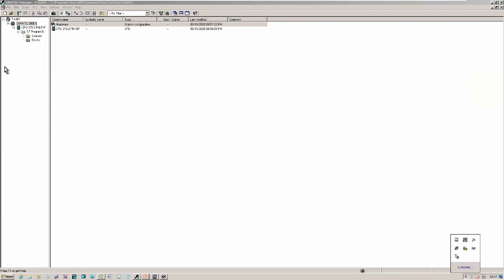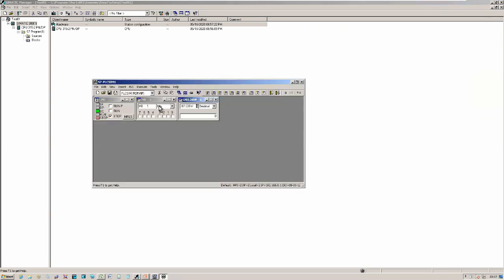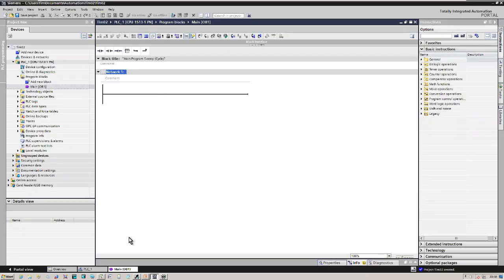Okay, I'll have to demonstrate another time, but let me just show you in my simulator what should happen. You see, I've already got marker byte 1 in the simulator. It will actually show you these bits going on and off as the PLC scans, and that's exactly how it works in the PLC. If I go to TIA, they have a similar feature.